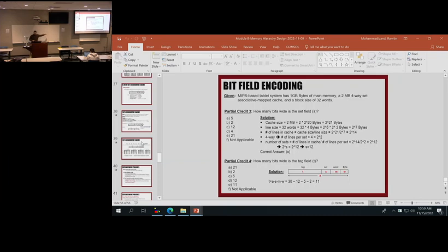Find the byte first and then find the word first. So that's the whole idea. We don't want to have a huge circuitry handling all this, activating different parts of the line. But the whole concept of working with memory is about how you activate different lines of words, and it's going to find that location. We usually have sense amplifiers, for example, like you have a sense amplifier connected to this. You activate that word line, and it's like routing. It's a routing problem. These routes are connected. It's like a network. Everything is routed. Every cell is routed, and then you have switches, and you specifically select that specific location through that routing.